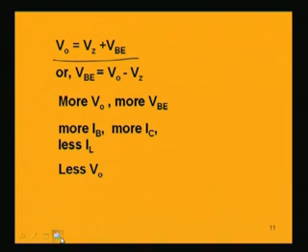That means we have initially increasing V naught, but as increasing V naught shunts away more collector current, then finally the load current IL will be decreasing. That means V naught will be also decreased and it will be maintained at that same level. So this was a shunt regulator using a simple circuit.